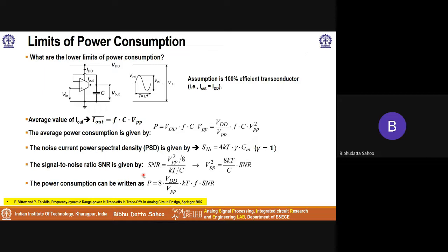Then we'll talk about, in the context of one of the major blocks, which is the data converter, either an ADC or a DAC, how scaling and other things impact the performance. The reason I'll talk about that is low power is achieved because of scaling, where we scale the devices, resulting in the voltage supply being scaled and therefore the power being reduced. So I'll talk about that.